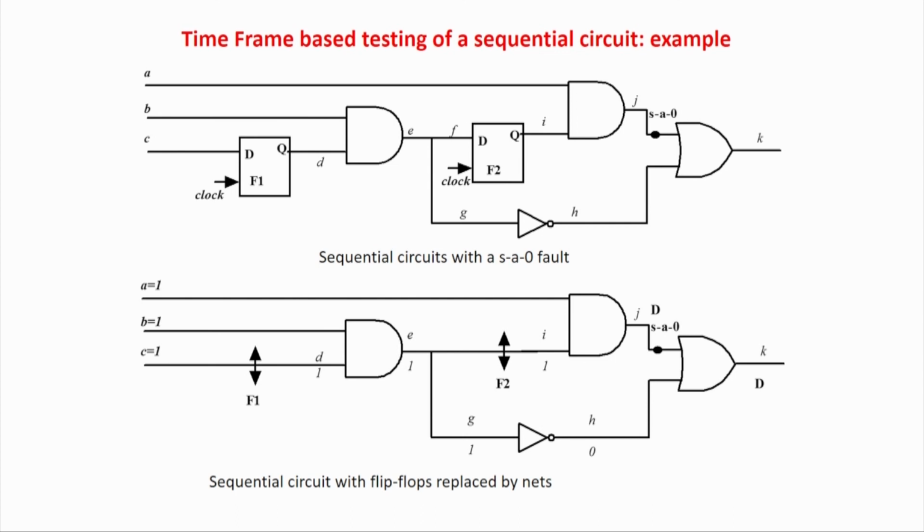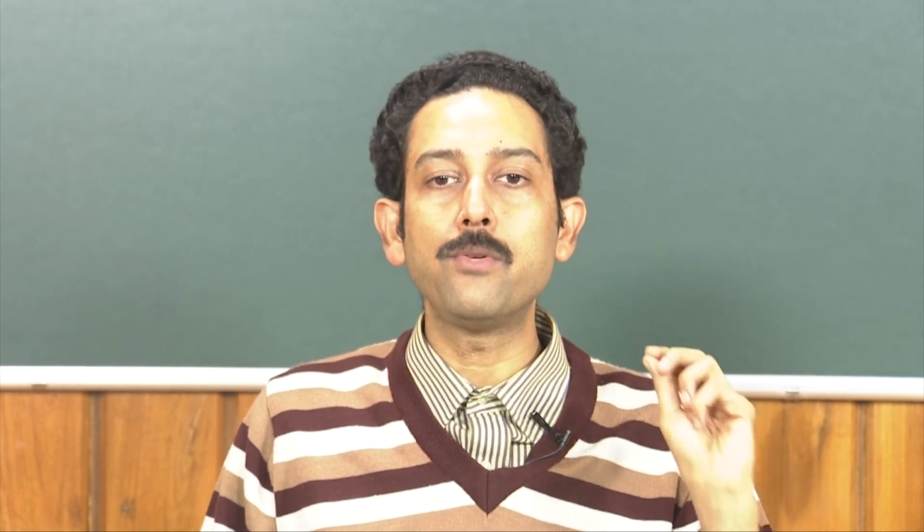So you require test patterns and 10,000 clock pulses to set it, and in the case of scan it is the same story. So generally, scan chains may not directly help you to solve the test application time. They generally only help to minimize the time required to generate the test patterns.